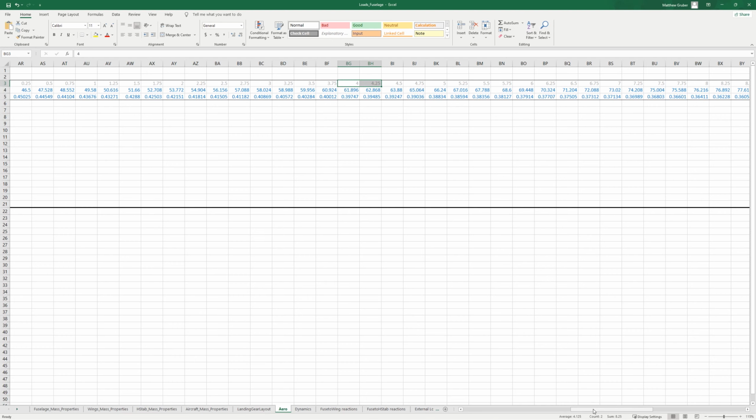Just for reference, if your angle of incidence of the wings is, let's say, 3 degrees, then the overall aircraft is at an angle of attack of 4.1 minus 3, which is 1.1. That's what you can adjust: the HStab can adjust the overall angle of attack of the whole aircraft. We can't change the angle of incidence of the wings.